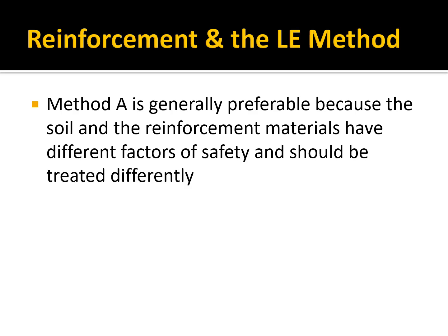So method A is what is generally used in the calculations when you do reinforced slopes using the limit equilibrium method. And most slope stability software allows you to do reinforcement, including UTexas and the educational version of UTexas. And so in our in-class exercises, we will be going through several examples of how you would go about putting in reinforcement and then how that impacts the factor of safety.